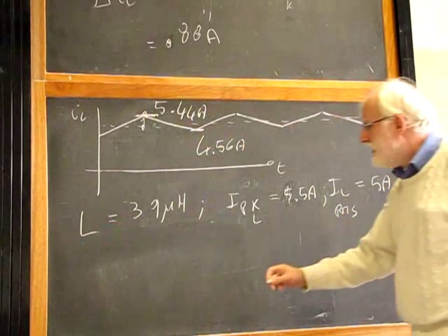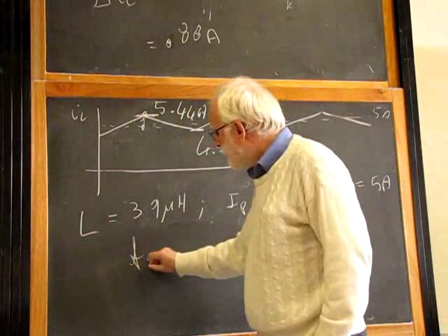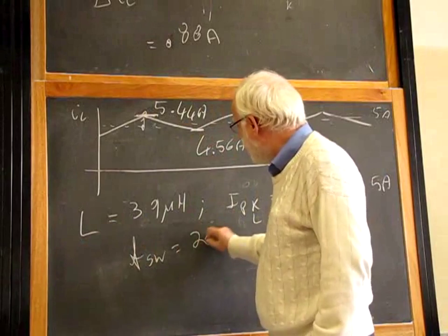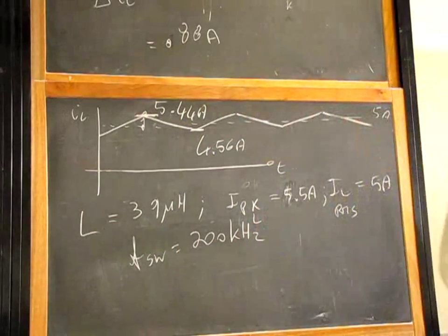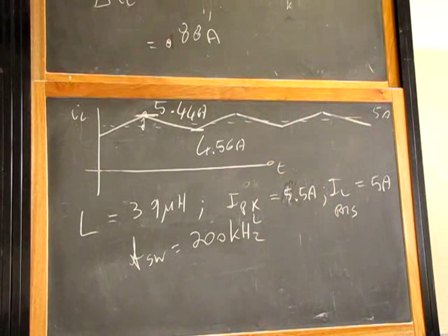And you still have to add the switching frequency for your inductor, which is 200 kHz. And that should be enough to choose your inductor component from a catalog. Most of the time, the inductor is already manufactured and available on the market. So far so good?